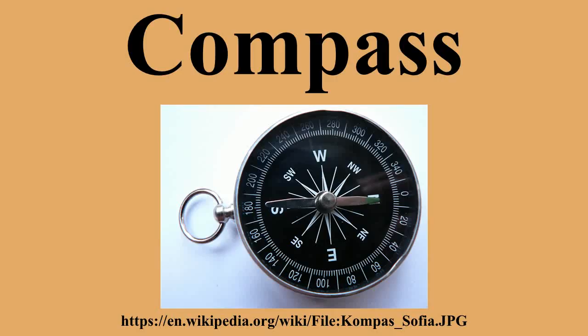Except in areas of extreme magnetic declination variance, this is enough to protect from walking in a substantially different direction than expected over short distances, provided the terrain is fairly flat and visibility is not impaired. By carefully recording distances and magnetic bearings traveled, one can plot a course and return to one's starting point using the compass alone. Compass navigation in conjunction with a map requires a different method.